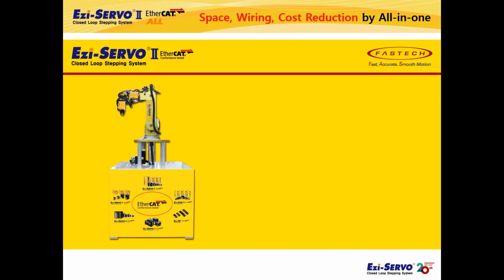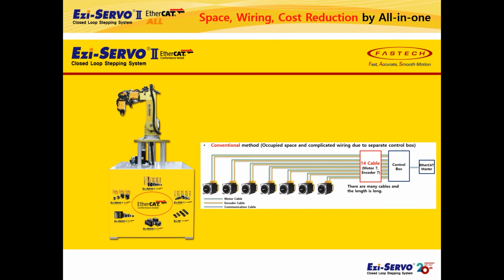Finally, with a 7-axis robot as an example, I will explain space saving, reduced wiring, and cost reduction by Ezi-SERVO II EtherCAT ALL. In general, to operate 7 motors attached to a robot, it requires 7 motor cables and 7 encoder cables. A total of 14 cables have to be connected to the drives installed in the control box, so wiring is not easy.